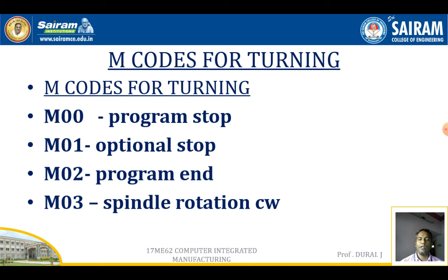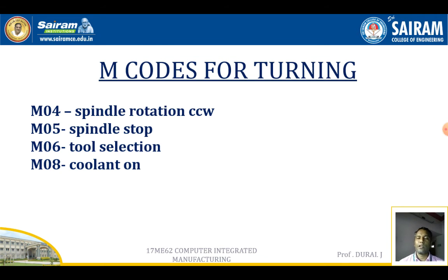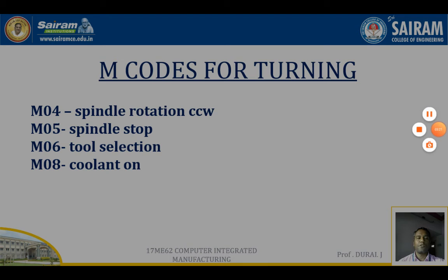Then comes the M03, spindle rotation in the clockwise direction. Suppose we want to rotate the spindle in the clockwise direction, we have to use the M03 command. In some operations we have to use the counterclockwise direction. Those times we have to use the M04 command.